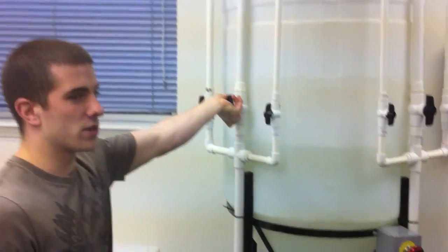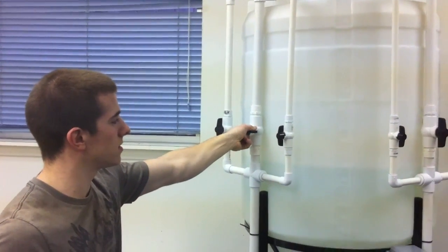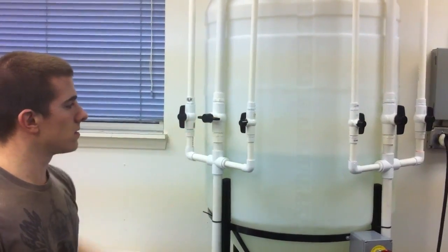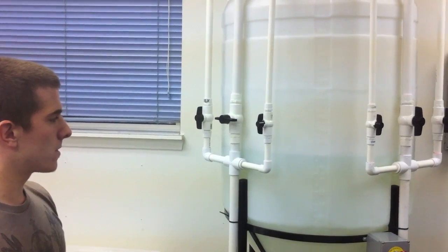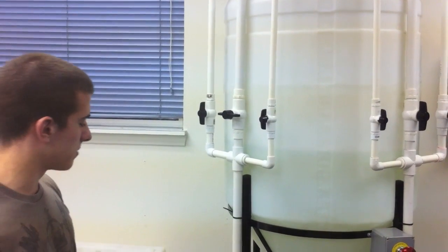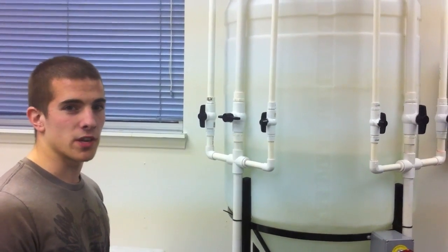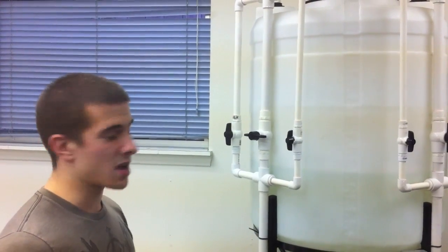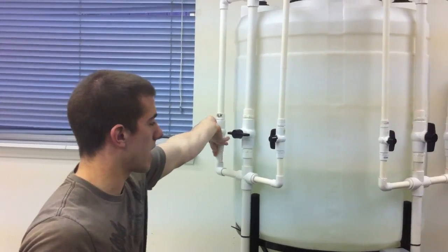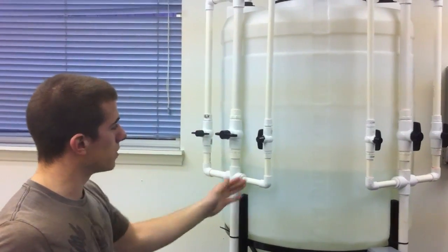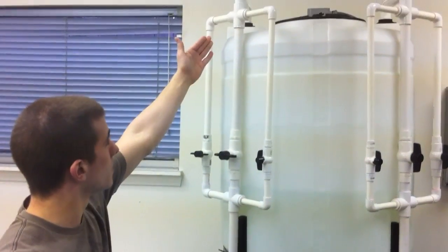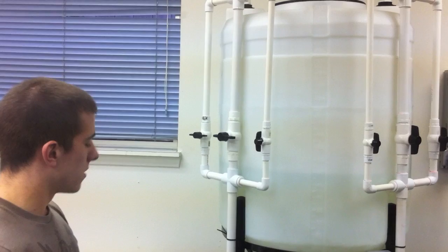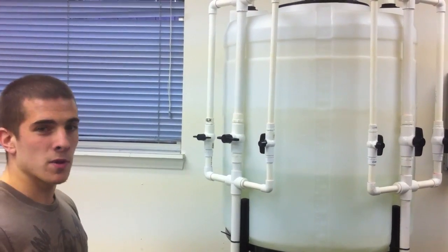As you can see, it's reached 50 gallons now, so I'm going to close the 1 inch valve and see how it reacts. To compensate for that, it simply increases the duty percentage of the pumps pumping into the tower tank. So it seems to be keeping that pretty well, so now we'll go down to the 1/2 inch size. So now the water is only flowing through this 1/2 inch pipe up into the 1 inch into the tower tank, so the pumps speed up.